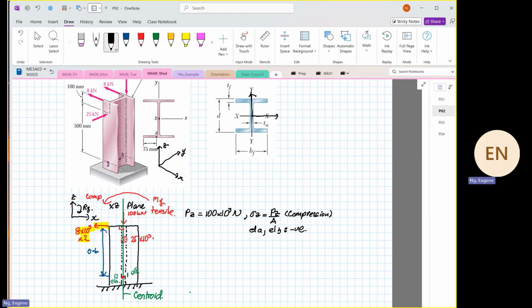So over here, you just do the calculation now. You declare that going in the anti-clockwise direction is positive. Then you're going to calculate the moment in the y direction, because this is in the y direction. We are very sure it's in y direction. So it's equal to what? It's equal to force 8 times 10 to the power 3 multiplied by twice, front and back, multiplied by the perpendicular distance of 0.6. So this will be equal to 8 times 10 to the power 3 times 2 times 0.6, which is equal to 9,600 Newton meter.